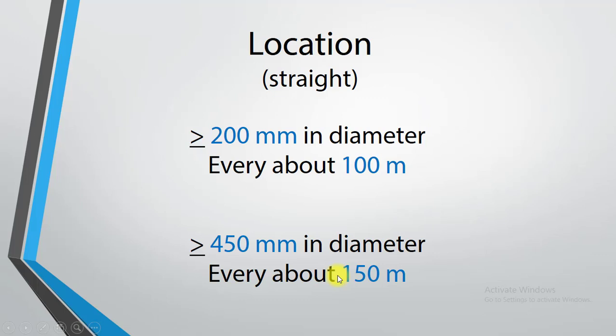Okay, why must we place a manhole, although there is no reason to place one? There is no change in size, diameter, gradient, or anything else. So here we can say that this manhole is only for maintenance. Imagine that we have 500 meters or 1 kilometer of straight line. If a blockage happens during this long distance, how are we going to inspect and detect the exact location? So placing such manholes will make it easier for the maintenance work to take place.